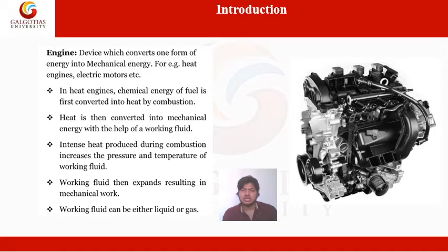So in a heat engine, the chemical energy of the fuel is first converted into heat by combustion. Then the heat is converted to mechanical energy with the help of the working fluid. The intense heat produced during combustion increases the pressure and the temperature of the working fluid. The working fluid then expands, resulting in mechanical work. Working fluid can be anything, either liquid or gas, which is used to carry the heat.